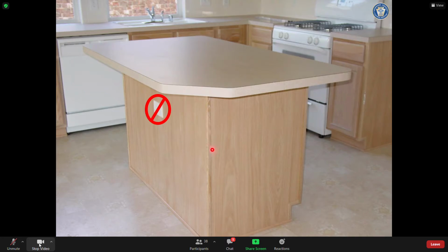And he wasn't as smart aleck as I was, but what they actually did here was they took this countertop off and set it over to the side, and then they rebuilt this cabinet to where on each end here and down here you only had an overhang of 1.5 inches or so. In other words, they expanded those cabinets. The homeowner gained more cabinet space by the AHJ doing his job. And they ended up locating the receptacle right here under that 1.5 inch overhang and satisfied this rule.